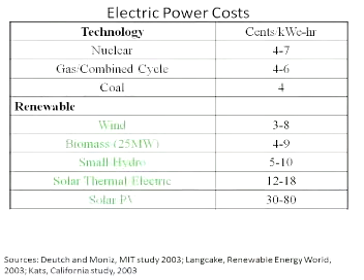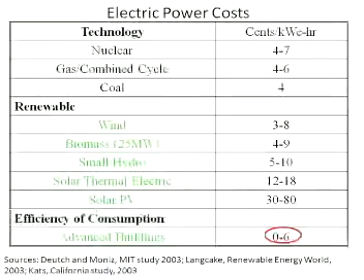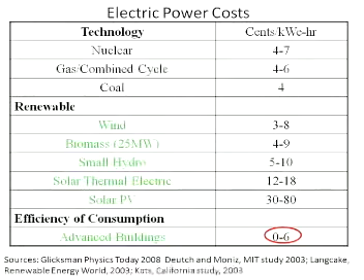If I have a new building, we may want to invest some more money in the capital cost up front to reduce the energy demand. If we look at what the cost of that is, down at the bottom in advanced buildings, based on a study done in California, the cost of saving a kilowatt hour ranges from nothing to 6 cents a kilowatt hour. Why nothing?